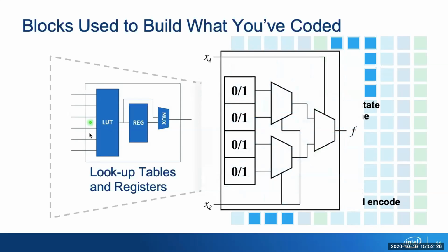So inside a lookup table, we have this kind of structure. This is a 2-input LUT, or lookup table. And we have multiplexers. The inputs are the controls of the multiplexers. And we have input bits here, reconfigurable input bits.